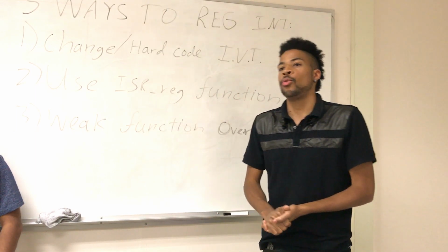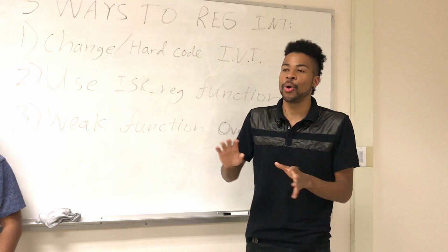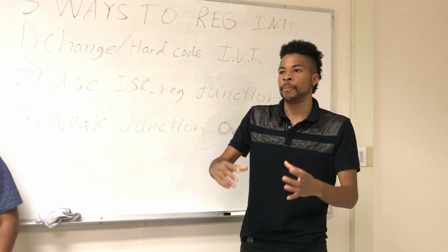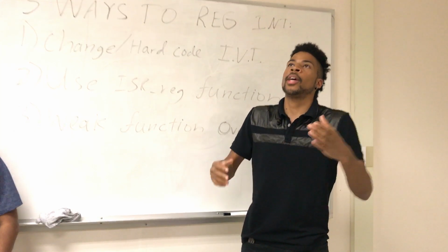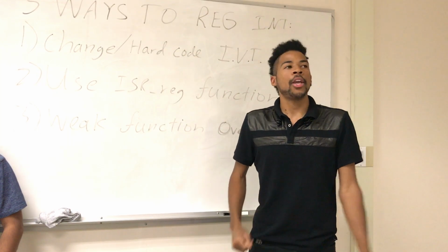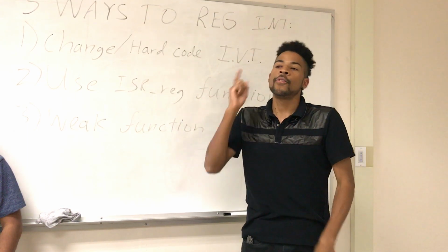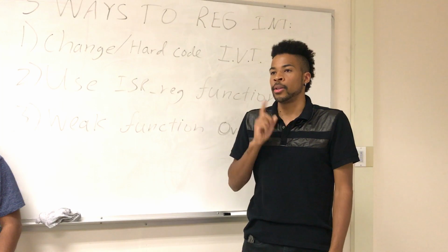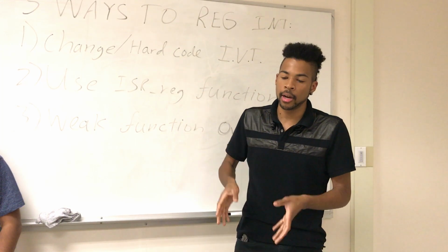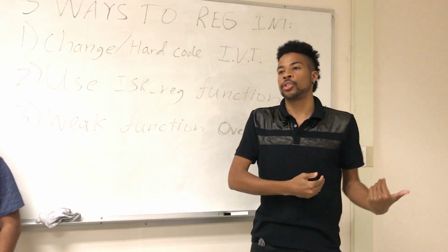For example, let's say you had, I'm not gonna use a linked list because in this case you won't want to use a linked list. Let's say you had like this array. And let's say that pin 5 of port 2 got triggered. When you're searching through this entire register to find which bit has been set, you find that it was pin 5. It was the one that got triggered. You would then search through your structure for that particular service routine, and then you would execute that service routine. But you had to have stored that inside some data structure somewhere else.